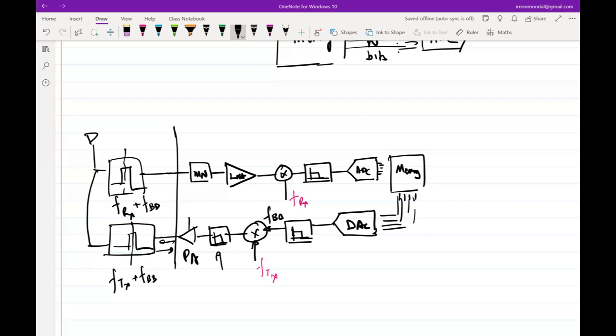If you want to reduce the gain of the PA, then you are effectively saying whatever is driving the PA needs to have a high swing. Right? Because let's say at the output of the PA, I want a swing of plus minus 1 volt, and the gain of the PA is 10, not dB, 10. So you are anticipating the input to be plus minus 100 millivolt. Now, if I reduce the gain of the PA to 5, then I am expecting the input to be plus minus 200 millivolt, because the output power of the PA I don't want to compromise, because that's a spec.